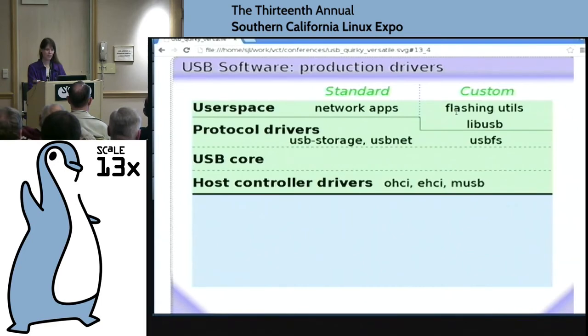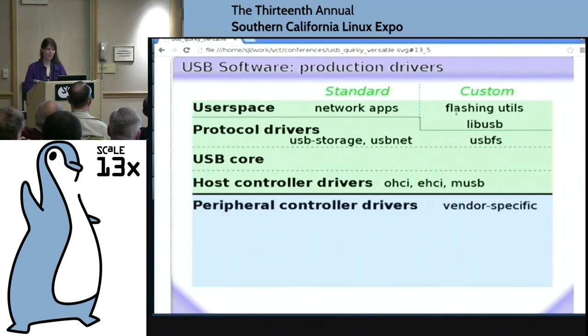Okay, so now we're going to go upside down because it's in kind of a nice symmetry, but this is actually the lowest level. From the target perspective, the analogy to the host controller drivers is the peripheral controller drivers, and I've found that this tends to be a lot more vendor specific. There's the Intel one, there's the Atmel one, there's the TI one. They haven't standardized as much as the EHCI, where it used to be Intel's vendor-specific one, but other people adopted it. So now things are happy because you have a pretty standard interface. We're not there yet with the target equivalent.